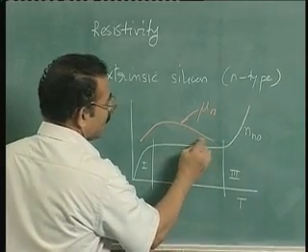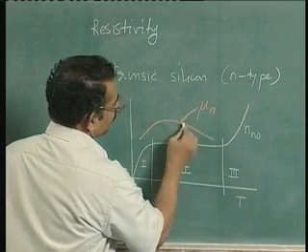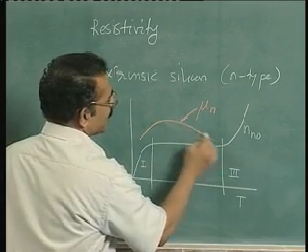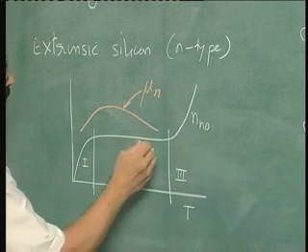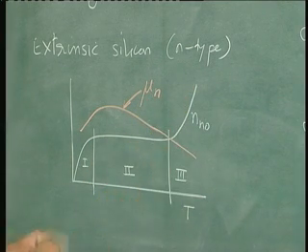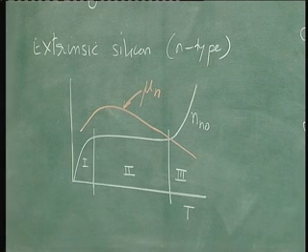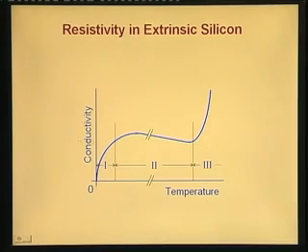So it is evident that you will get a rise and then in this range a fall in resistivity, a fall in conductivity because of fall in mobility. This is happening because of lattice scattering, and then because carrier concentration is increasing you again have a rise in mobility. So that is how one can explain this particular behavior. This fall here is because of mobility behavior, lattice scattering, and this rise over a small region in the extrinsic range is because of ionized impurity scattering, because in this range the carrier concentration is constant. So whatever variation you see is mainly because of mobility.